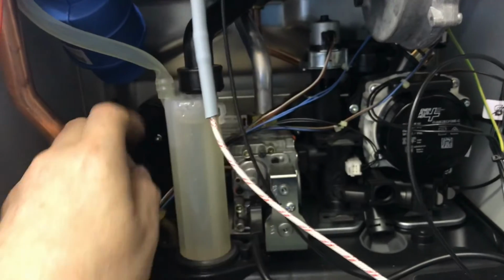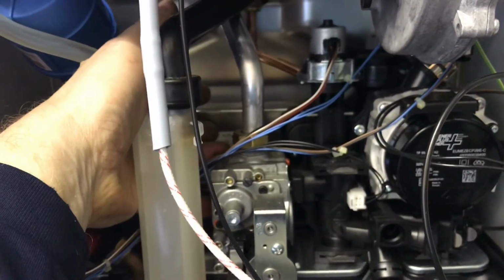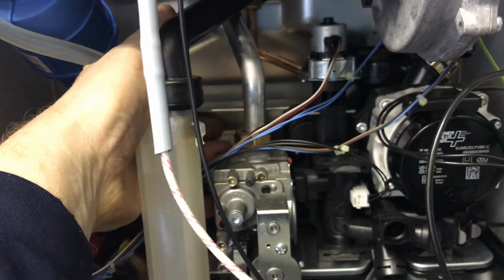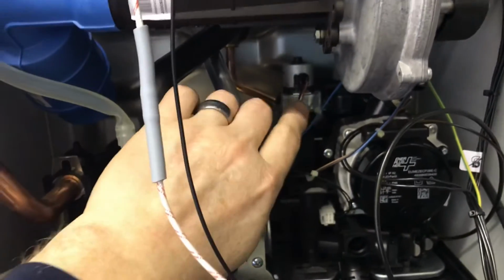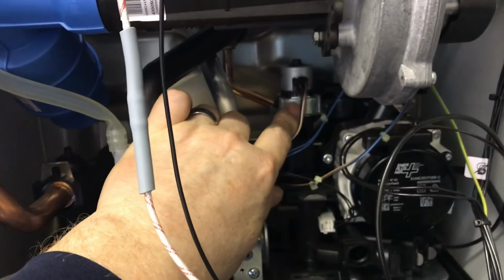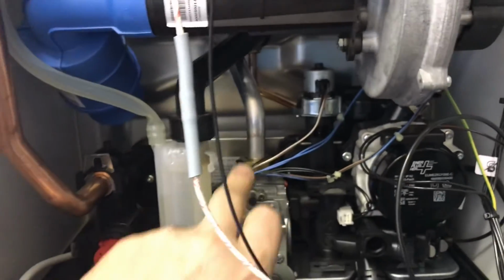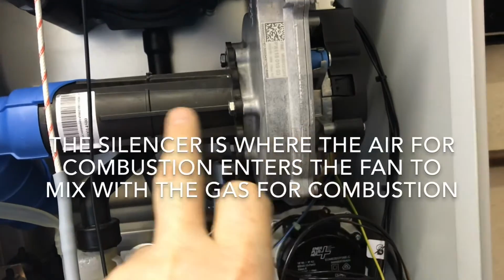At the back here where you see the arrows, this is the plate-to-plate heat exchanger. This is where the heat is transferred from the central heating water to heat the cold water coming in to give you hot water. This is the diverter valve, which is used to divert the water from the heating around the plate to plate. This tube now is going up to the fan, and the fan now sucks the gas in.